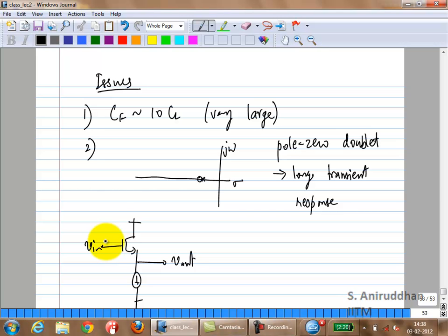Exactly. In the earlier case when you had CL, you actually have a capacitive division effect. If you don't have CL, now you can say CGS is a short, right? Then your gain at high frequencies is actually 1. You can pretty surely say at low frequencies it is actually less than 1. At high frequencies the gain is definitely equal to 1, right? So you actually see an increasing response. So if you plot the gain of this, it will do something like this.